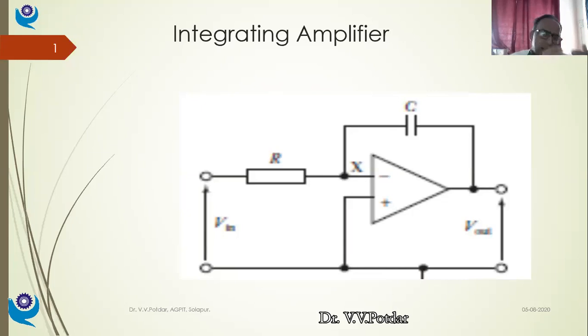So this subtraction of the input signal with the feedback signal can be done by using OpAmp. So OpAmp can be used as a comparator even. And then whatever is the error signal, that can be amplified further, and that amplified signal can be given to the actuating device, maybe a heater in this case, or a temperature control system. And accordingly, the temperature of the system rises till I attain 300 degrees Celsius. So this OpAmp can be used as a comparator.